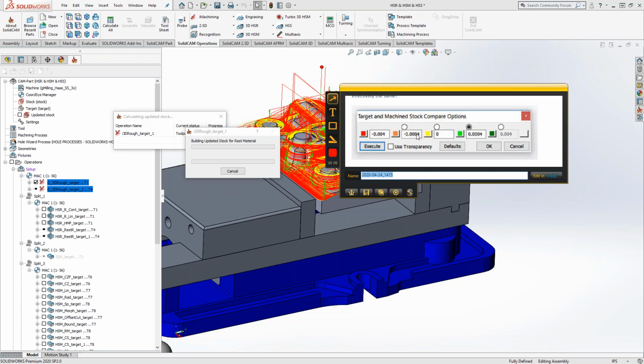your facet. You want this to be seen as either a flip up or a flip down, because if you make this anything smaller than your current facet, then this guy's not really going to tell you anything, because you could have that facet flipping in the wrong direction, indicating a gouge when it's not really a gouge. If anything, make this lower and make this one your actual size of your facet. That way you can at least get some accuracy on this side than this side.